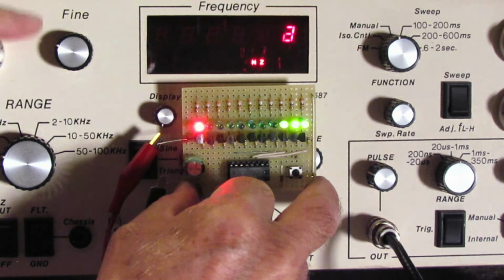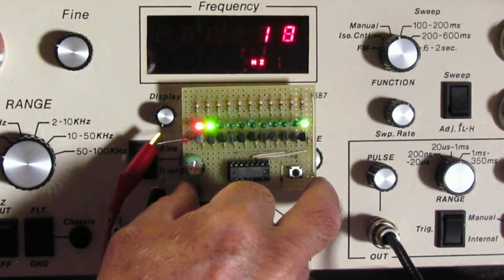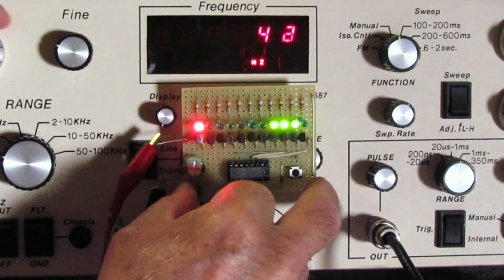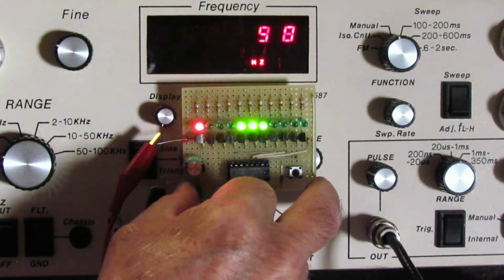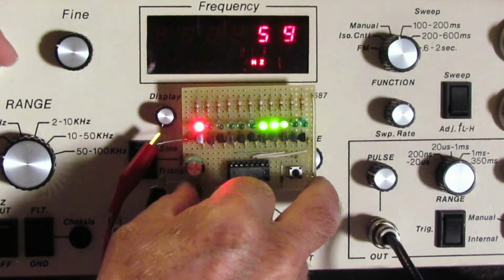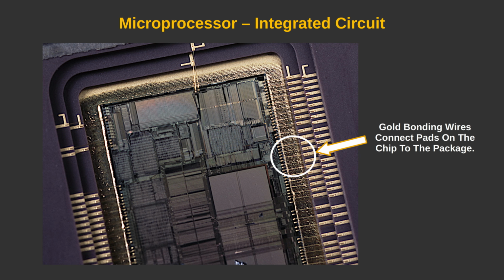I used binary coded decimal counters to design the frequency counter in the pulse generator. Binary coded decimal counters output 4 binary bits for each digit to decoders, which then drive 7-segment LED displays. The clock signal in this instance is applied to the counters for exactly 1 second, and the accumulated count is displayed. This is the frequency output by the function generator in cycles per second.